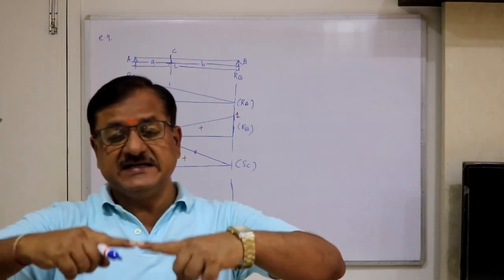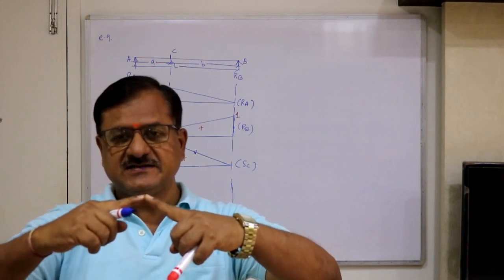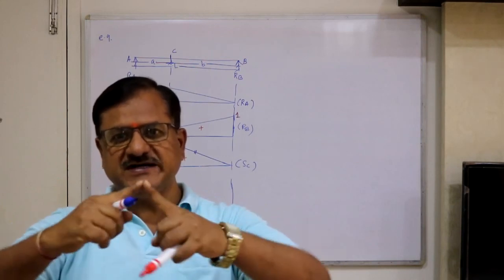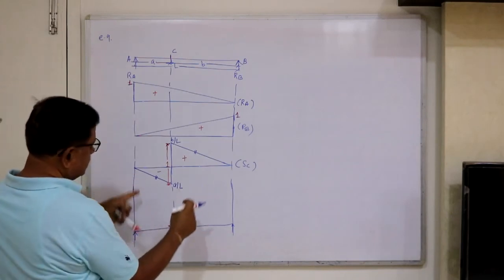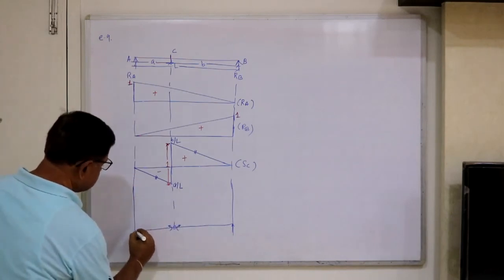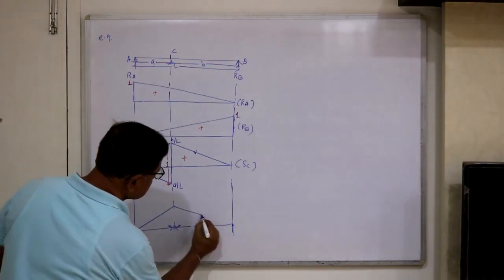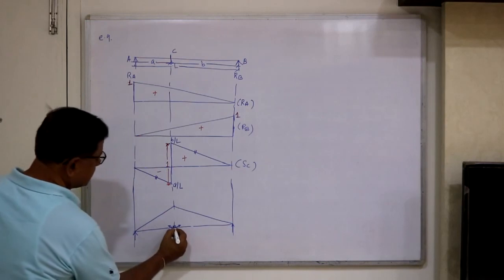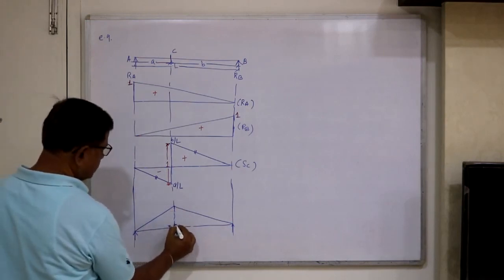Bending moment is released, but the bars are not allowed to separate, so shear is not released. Only bending moment is released. So when we rotate, it gets lifted like this, the ends are connected by hinge and not separated, and this ordinate is what we have to find out.